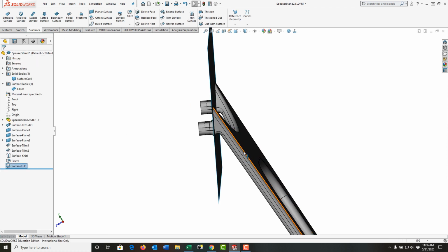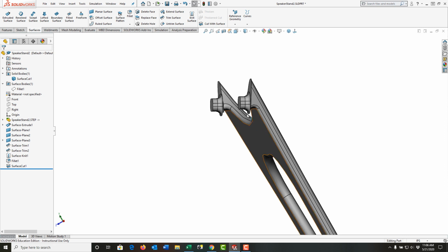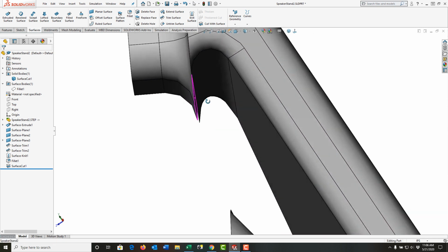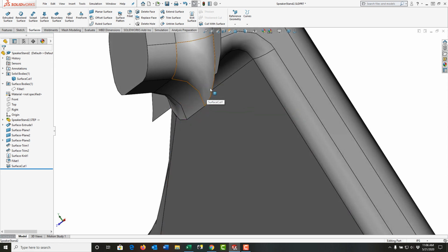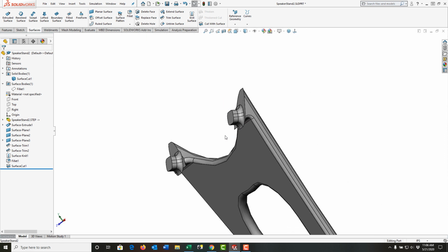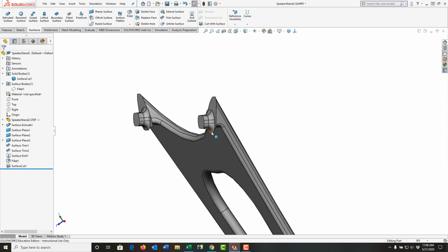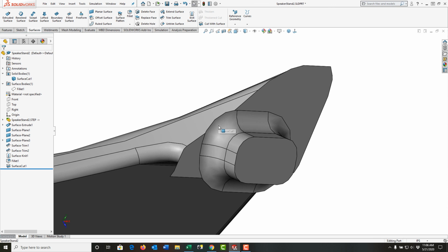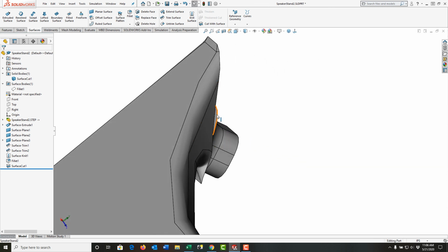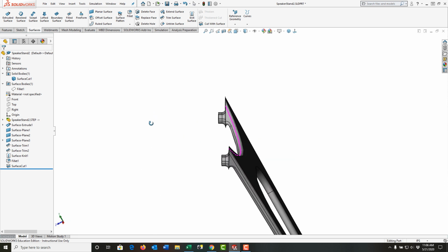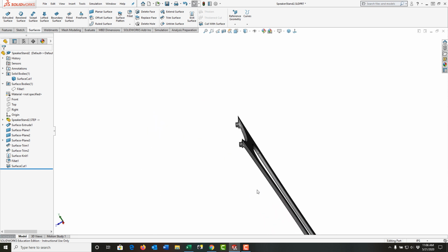And now we can see what I'm left with is this body. I'm just going to hide the surface. So there's my body that will push into the other one, and if I zoom in, I might want to rethink this fillet. But it will work. It'll even 3D print. It just won't be very nice here. And I have a bit of an issue here. So I really should play with these, but this is how I will separate them into two solid bodies.